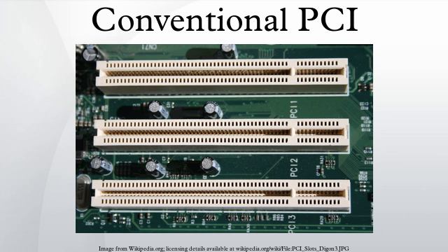The data phase continues until both parties are ready to complete the transfer and continue to the next data phase. The initiator asserts IRDY when it no longer needs to wait, while the target asserts TRDY. Whichever side is providing the data must drive it on the AD bus before asserting its ready signal. Once one of the participants asserts its ready signal, it may not become unready or otherwise alter its control signals until the end of the data phase.